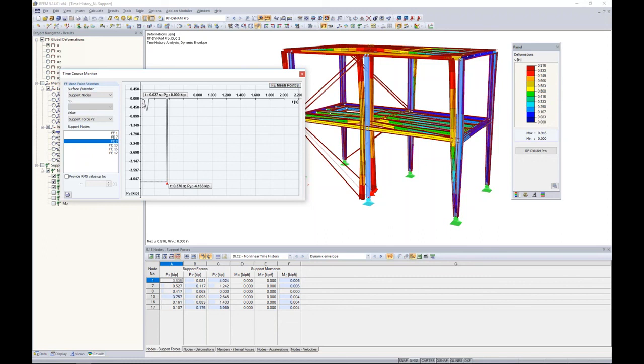We have uplift, but then at about time 0.027, it looks like we have some type of downward force, so that support is reactivated. Then it fails again. And then at about time 0.354, it's activated again for a short period of time. And then for the duration of the 2 seconds, it's completely failed, most likely because we have uplift forces here.